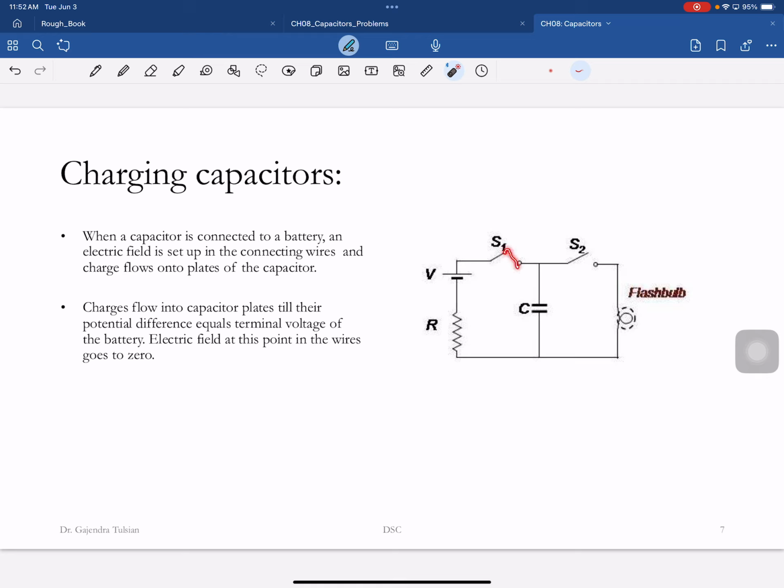when you close the switch, that's when that amber light is blinking, when the capacitor is charging. And when the capacitor is charged, that light goes green, the switch opens, and you're ready to take a picture. Okay. And then when you click your camera, you close this switch, and the capacitor discharges through the flash bulb.